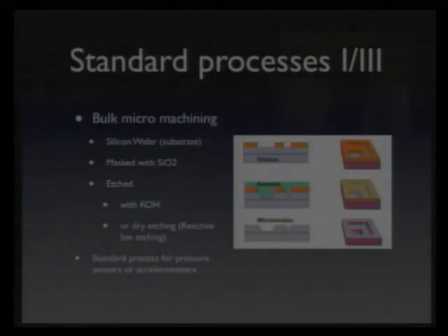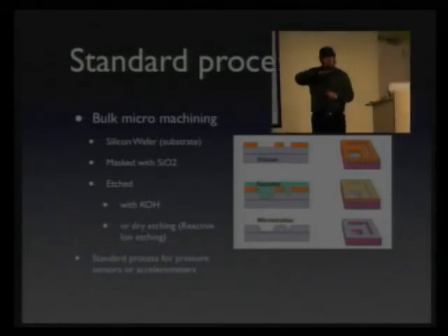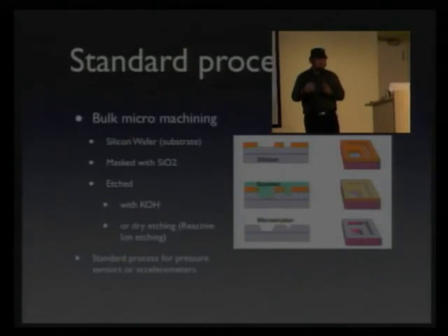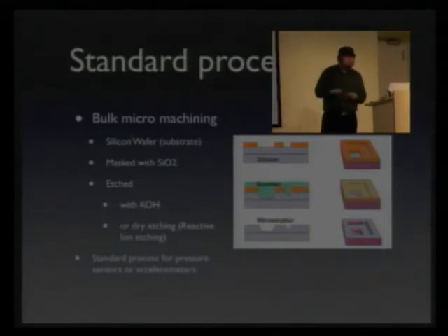Then you take a thin film resist, which is a photoactive polymer, put it on top, structure it with light, and then you have openings to the actual glass wherever you want them.